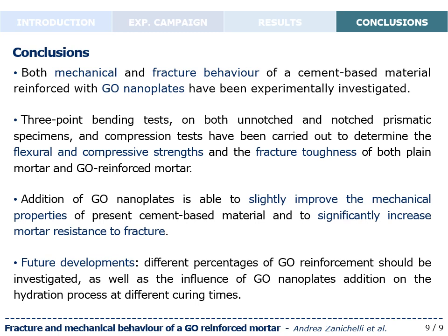GO-reinforced mortar. On the basis of the experimental results, it can be concluded that the addition of GO nanoplates is able to slightly improve the mechanical properties of the present cement-based material and to significantly increase the mortar resistance to fracture in agreement with the results reported in the recent technical literature.